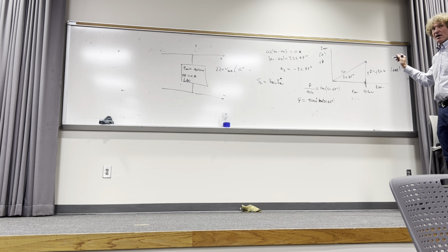Okay, now, y'all see what they want there? We've got it, right? But what do they want? They want a power factor of 0.9, right? So that means what they want to do is reduce this angle or reduce the amount of reactive power. Can everybody follow the thoughts here?